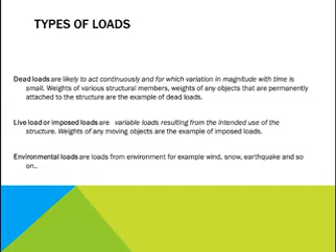Basically, the loads can be divided in three categories: a live load, dead load and environmental load. Dead loads are likely to act continuously and for which variation in magnitude with time is small. Weights of various structural members, weights of any objects that are permanently attached to the structure are the example of dead loads.